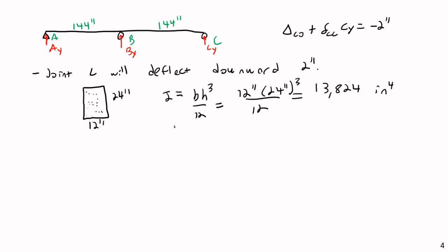And then our modulus of elasticity. So quite a bit of moment of inertia. This would be enormous for, say, a steel member, but of course we know this material is much less stiff than steel. Its modulus of elasticity is only 3,500 ksi in comparison to our usual assumed value of 29,000 ksi for steel. Now, I also want to consider what I know about redundance and things like that for the force method.